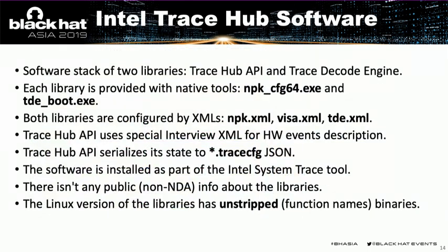Intel has developed a comprehensive software stack supporting the Trace Hub. Unfortunately, there is no public documentation on how to use the software. However, the software is provided as part of Intel Trace Tool, which is a component of Intel System Studio. The software consists of two large libraries, Intel Trace Hub IP and Trace Decode Engine. Intel Trace Hub IP is intended to configure Trace Hub hardware for various trace sources and set it up to transmit trace data via a number of hardware interfaces.